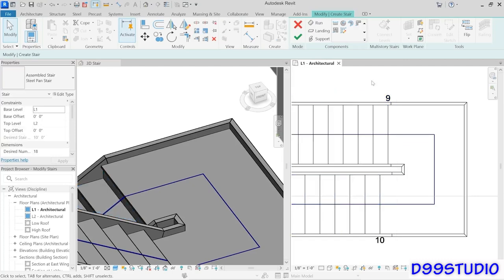Okay. Now, you obviously have to have enough room in your design to accommodate the larger landing. But honestly, in most cases, not only is this the simplest solution, but it's really the best solution because most building codes call for that kind of a configuration anyway. So if you're trying to follow a particular building code, there's a pretty good chance that it's going to require those kinds of clearances. And so the solution to both problems is as easy as moving the runs.